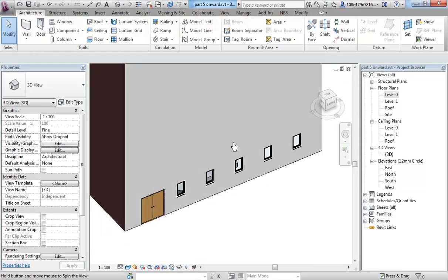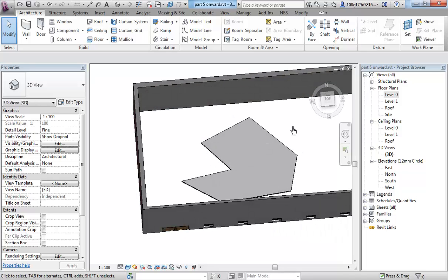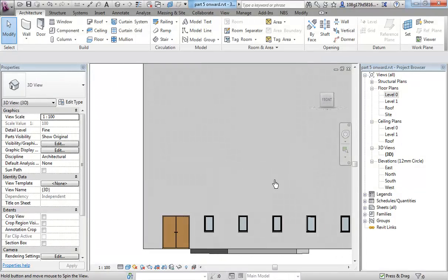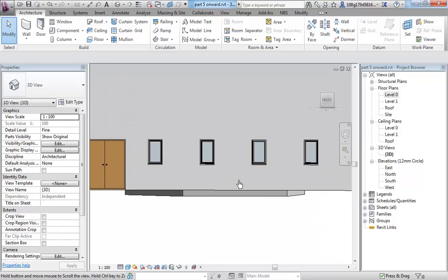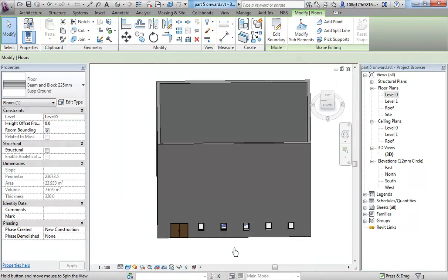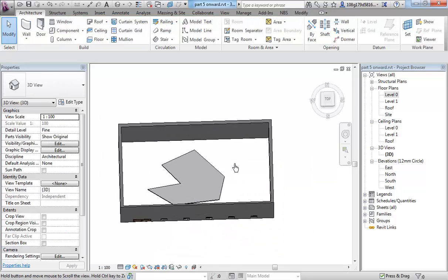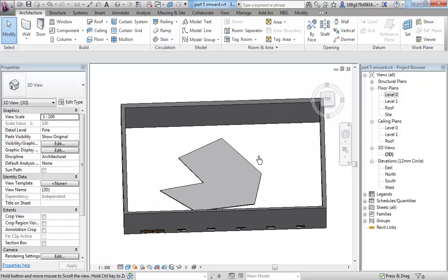Quickly jump to 3D mode to show what we've got, and we've got a random floor where the base of the floor is coming from beneath 0. It's 225 millimeters thick, and the top is 0 and it's moving downwards by 225, so the datum is referring to the top of the element. That is so if you're introducing things like office furniture onto this floor, you don't need to be thinking about the system that you're placing it onto.